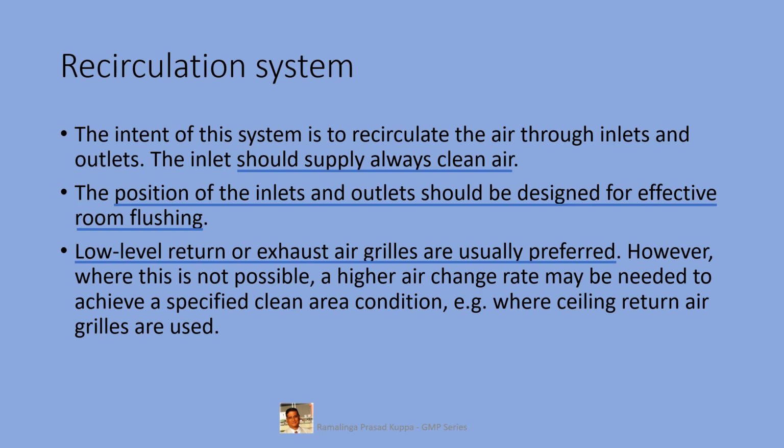Air changes per hour is a simple calculation. Air change rate is a measure of the air volume added or removed from a space in 1 hour divided by the volume of the space. Measure the area of the room, measure the height.